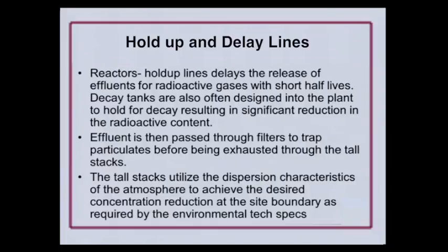We use compressors to put them in there. You compress it as much as you can to get as much gas in there as you can, and you just leave it for decay. Most of the fission product gases are short-lived. Usually within, I think, 8 days, it had decayed off enough to where it could be sampled, and then it would be fed out and discharged via the effluent stack.